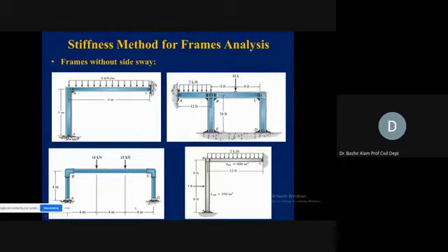Again, now let's say loading is symmetrical, but CD is not similar to AB. Because of the unsymmetrical geometry, again, this will become a side sway frame. Now, with everything else the same, but at D we are making this a horizontal support, I mean a roller support. Because of the unsymmetry, chances are there that it will become a side sway frame. But in the condition where you have perfect symmetry in the geometry and symmetrical loading also, there is no lateral displacement.